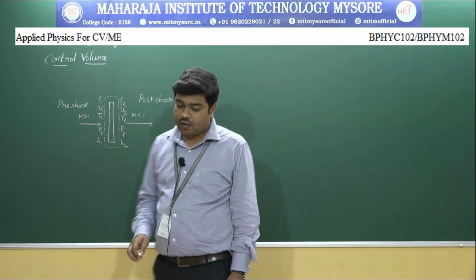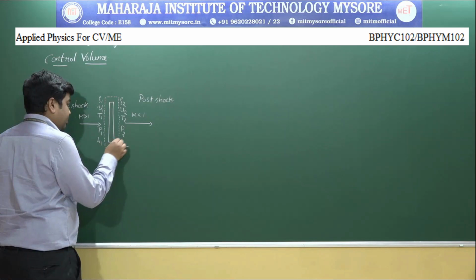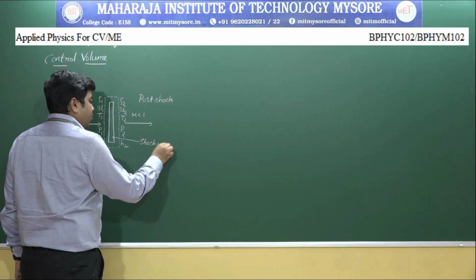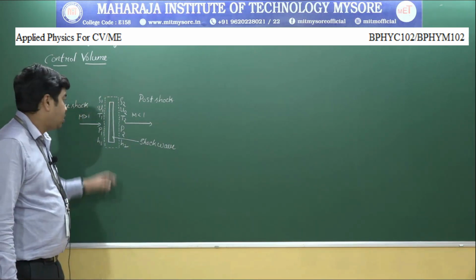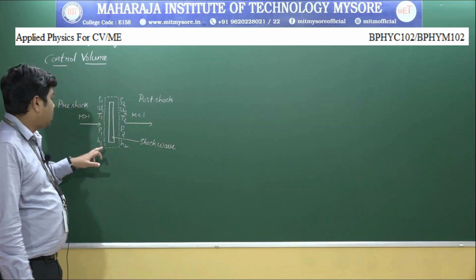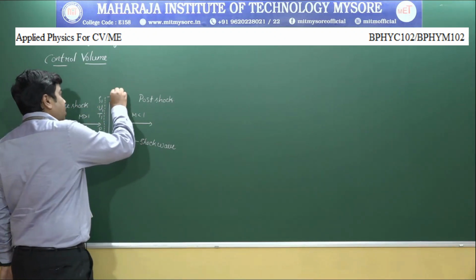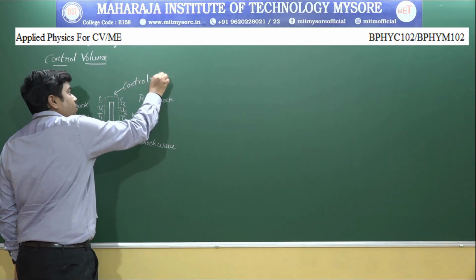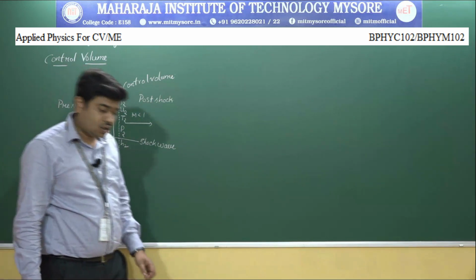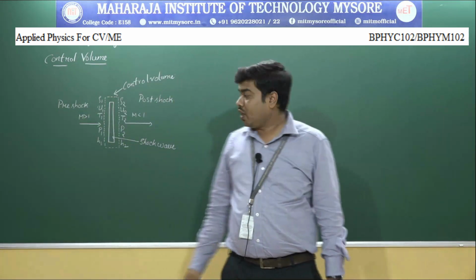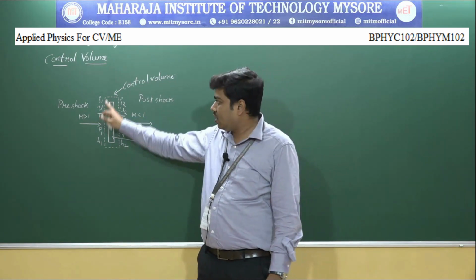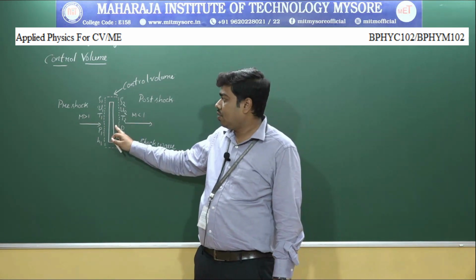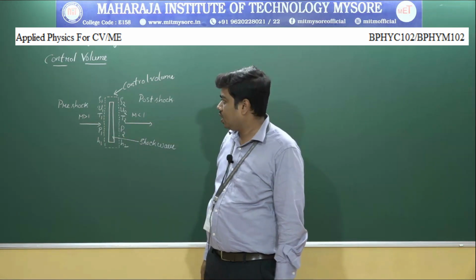Now as you can see, this is a shock wave, or a shock front part of a shock wave, and surrounding the shock wave you have an imaginary envelope, which we call a control volume, of thickness of about 1 micrometer, within which the whole area is compressed and there is a sharp increase in temperature, pressure as well as density.